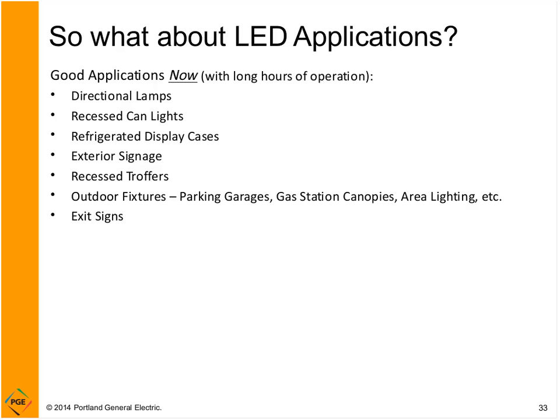Because LEDs like it cold, refrigerated display cases are a great LED option. Outdoor signage, very good place. Again, they like it cold. Recessed troffers, we've touched on that a little bit. These generally need to come down in price a little bit more, but if you have long hours of operation, it's definitely something to consider right now.